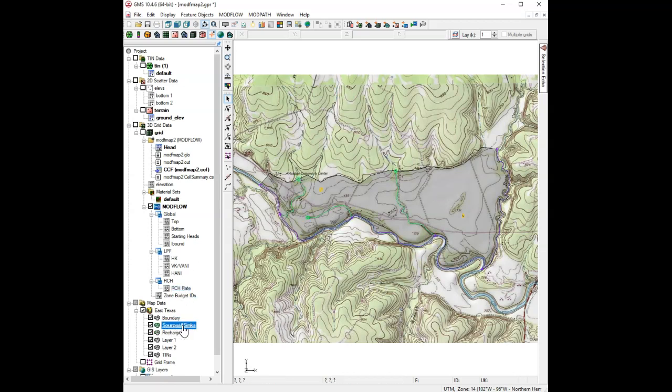As you may recall, there is a well here and a well here, and we have rivers on the bottom and on the right of this model. So the question is, what is the capture zone for this well over here? Does it include the landfill polygon? We're going to do backward tracking from the wells to get the capture zone for this well, and then we're going to do forward tracking from the landfill polygon, and use those two different sets of results to determine what impact this landfill would potentially have on the river and on the well.